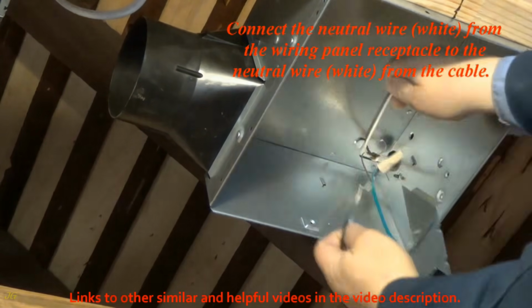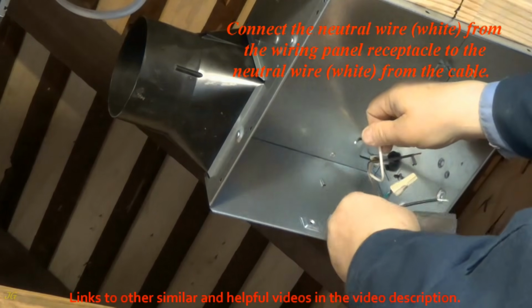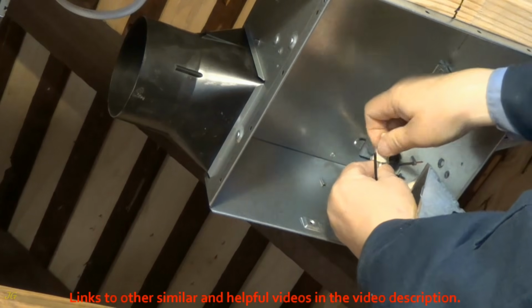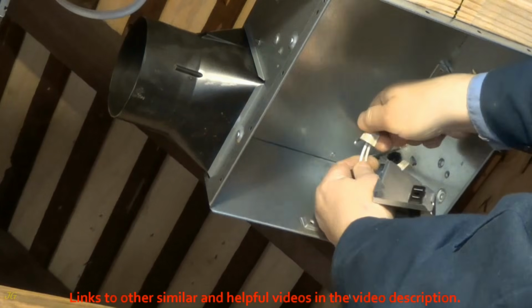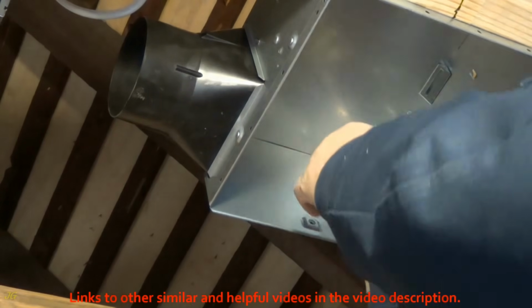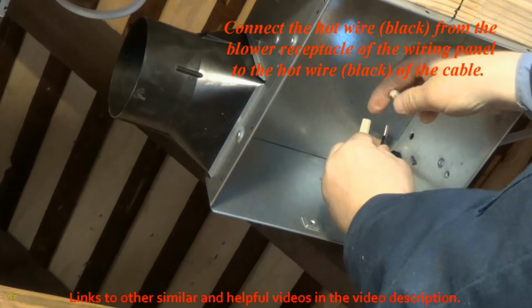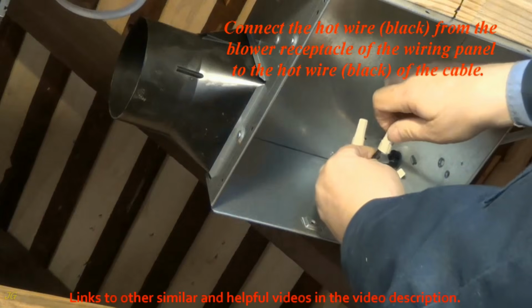Connect the neutral wire, white, from the wiring panel receptacle to the neutral wire, white, from the cable. Connect the hot wire, black, from the blower receptacle of the wiring panel to the hot wire, black, of the cable.